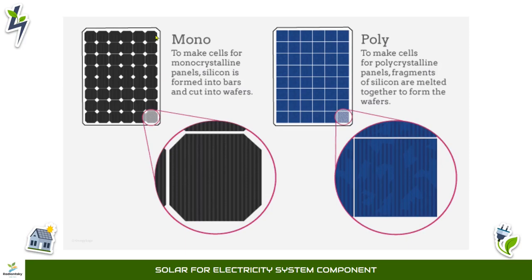So this is a mono panel. The easiest way to identify them is by their color. The wafer is always black in color, very dark black, and you see mono panel always having something like an edge cut. This is how the technology is built. It has an edge cut on the wafer. You see this design, like more like an edge cutting on them.